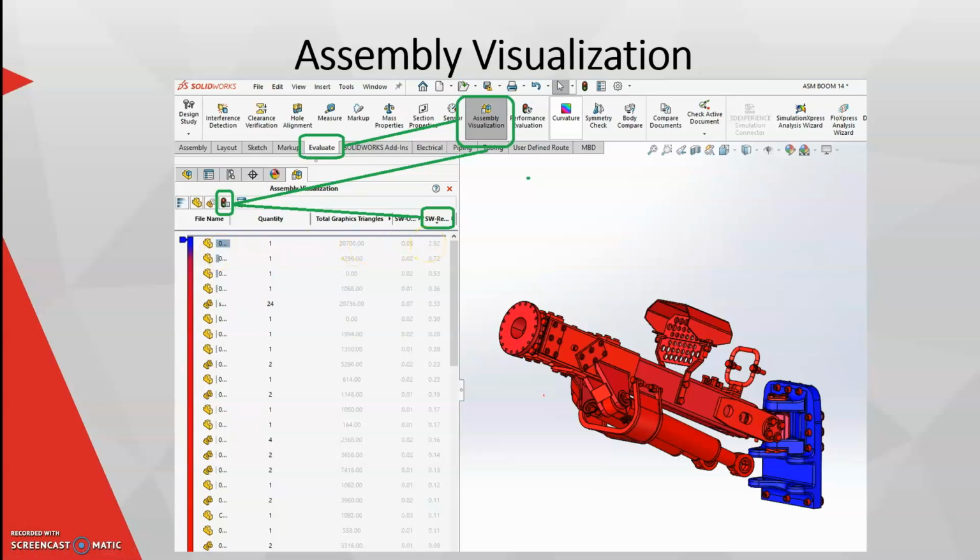This model itself is already very optimized, so there's no need for us to optimize it any further. But you'll see sometimes as well, it'll be like 50 minutes or like 1,000 seconds or 2,000 seconds. You know, then if that's the rebuild time, there's something wrong in that model. Okay. It also gives us graphics triangles, so it allows us to go and look at, maybe we need to push down tessellation on those specific parts, and stuff like that.